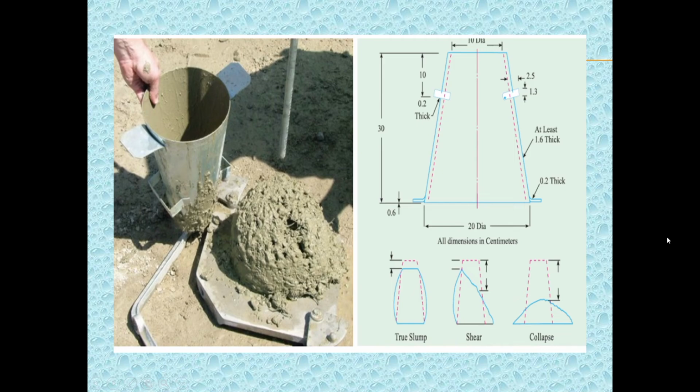Slump test is very useful on the site to check the day-to-day variations in the materials being fed into the mixer. An increase in slump may mean either moisture content of aggregates has increased unexpectedly or grading of aggregates has changed due to the deficiency in sand. Thus, too high or too low slump gives a warning to the mixer operator to remedy the situation.